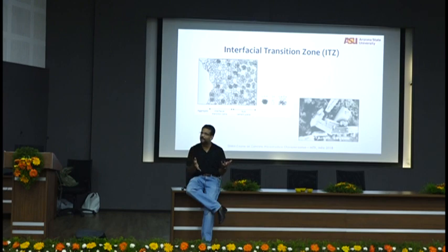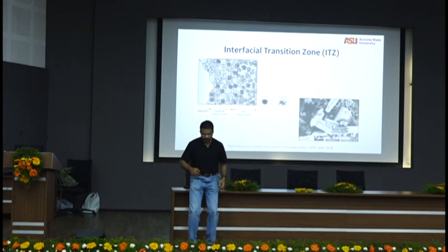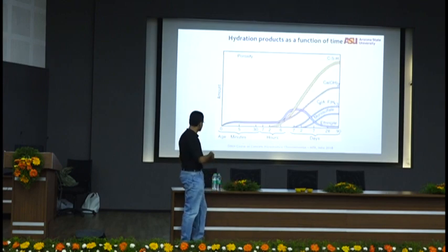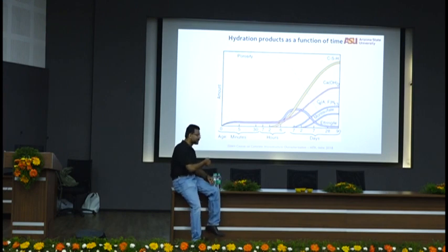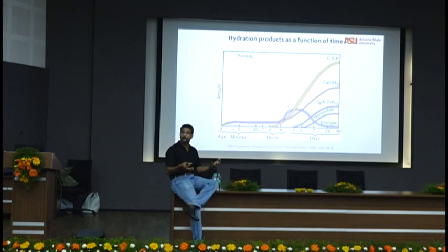Basically, what will you have then? You will have interlayer space there. And then calcium hydroxide, if you look at the previous picture, you will also see another interesting thing. What is forming first in this system? Calcium hydroxide and ettringite. Both of them are crystalline products. When you put different crystals together, you leave a lot of space in between the crystals, not like amorphous products, right? So, what is formed initially are both crystalline products.